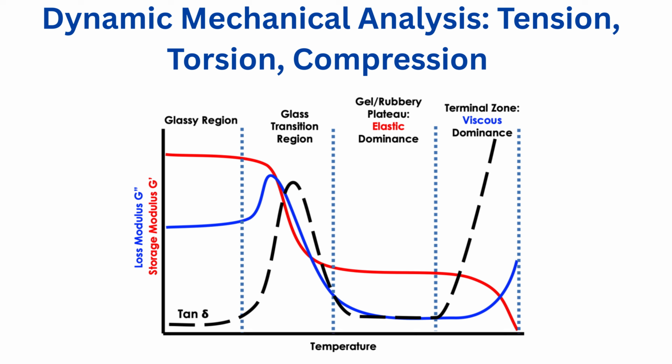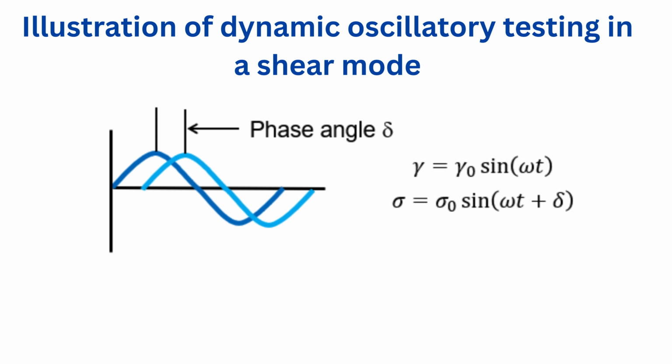The degree of cross-linking in a thermoset is a critical parameter that has a major influence on the mechanical strength and viscoelasticity of the material. For an unfilled thermosetting polymer, the percentage of cross-linking or the cross-linking density can be quantitatively calculated using both rheological and DMA measurements. Dynamic oscillatory testing is a very important method for characterizing thermoplastic and thermoset materials. It is usually the best way to determine a material's viscoelastic properties, which can be related to molecular architecture, processability, curing kinetics for thermosetting materials, and end-use performance.